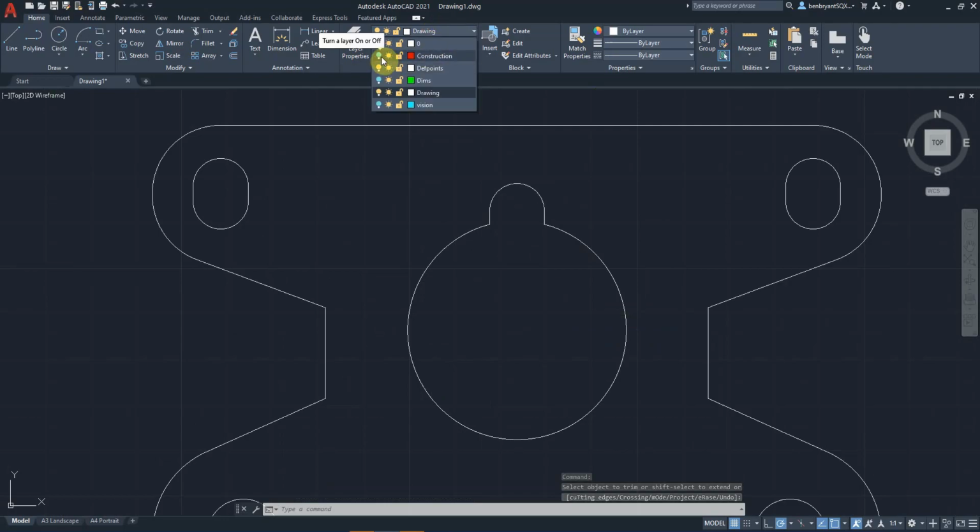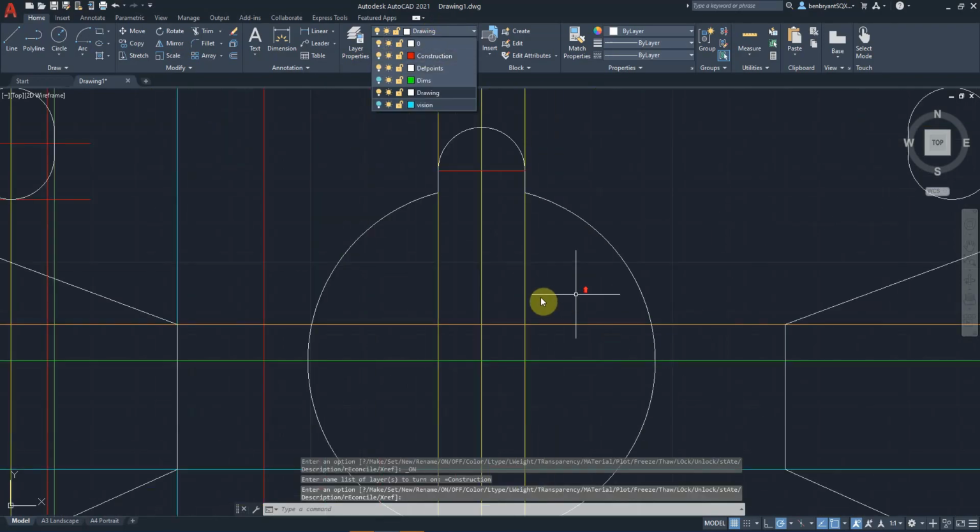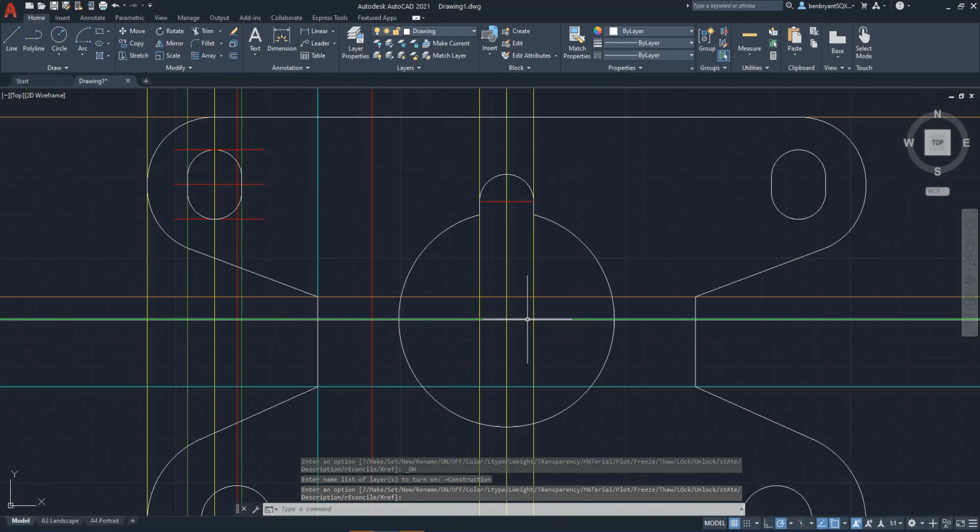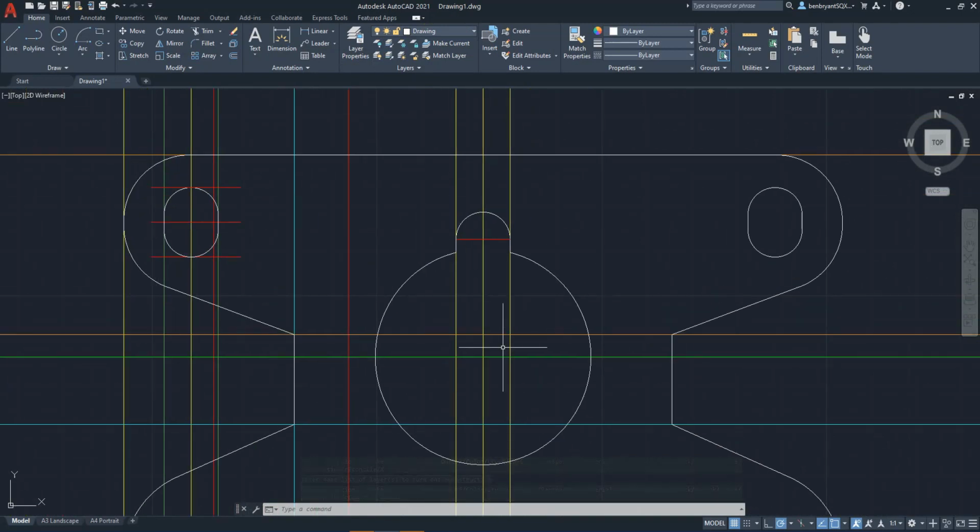So the last thing to do essentially now is we need to draw a line that's 45 degrees from our center point. So I'm going to do an X line from my center point. Choose the location, and obviously I can move that now to 135.